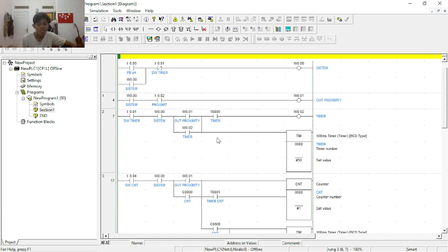And this is the PLC diagram. So in this rung or layer contains the proximity sensor input, and then include timer also, and then we can use set and reset instruction to make the motion sequence automatic. So for the result of this diagram, the pneumatic actuator can move accordingly. Okay.